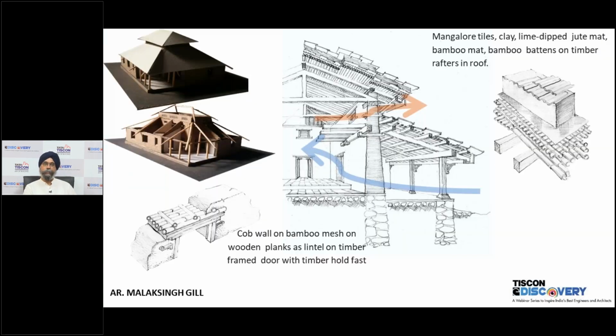Here you can see the entire shape of the building. It's a traditional shape, the same as which is used in Gandhiji's ashram also, Sevagram ashram there. You see the cross section of the building where you have the central core, which is almost 16 feet high, which has a mezzanine and a loft. You can see the roof, which is made in wood, but which has bamboo as the boarding.